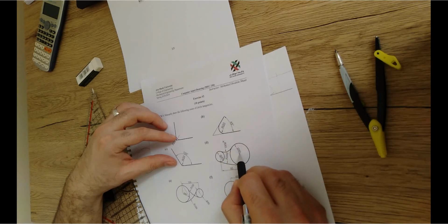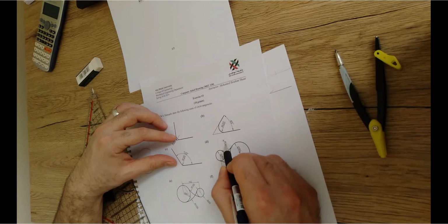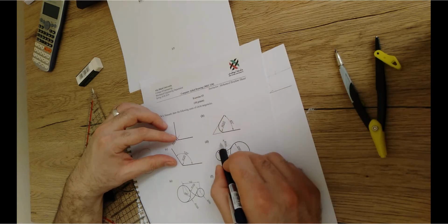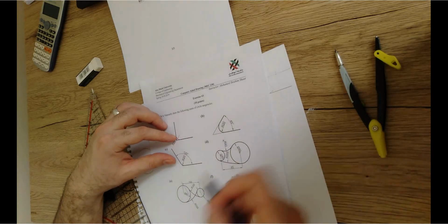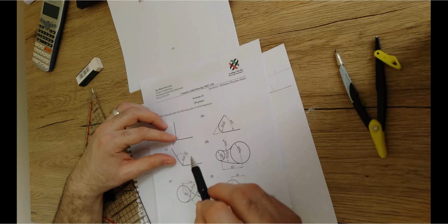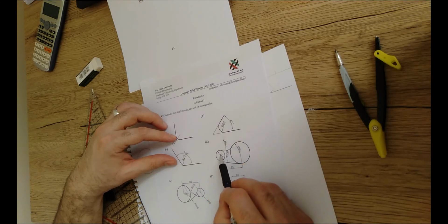So it means that I have to open the canvas and fix from this center of this circle by 40, the radius of this big circle, plus the radius of the curve itself, which is gonna be 40 plus 40 gives 80. And then I'm gonna draw an arc. This is gonna be the first locus. The same, if you ask yourself, how much is the distance between the center point to the center of the small circle?